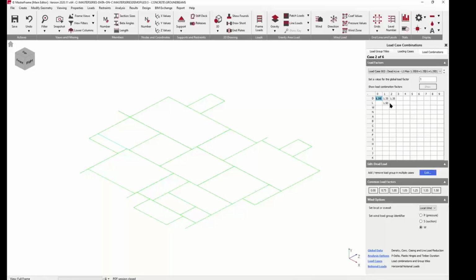In the Eurocode, which we're using, you could have got away with only a D1 for all the dead loads, but it's easier to work with than two separate values just for completeness. And then they'll reverse, minimum, maximum. And then we have the serviceability equivalents of those and nothing else.